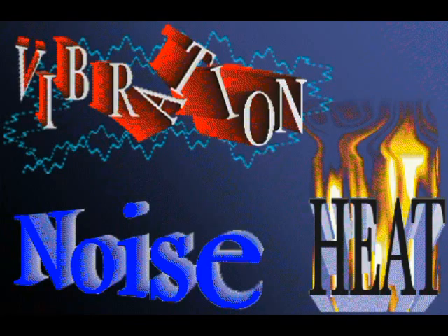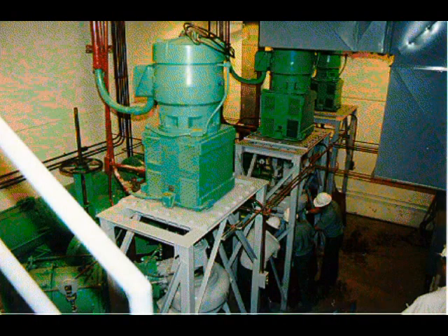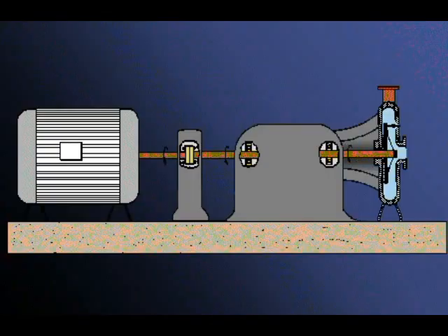Generally, noise, vibration, and heating are all indications of a problem and should be investigated immediately. If pump performance is not satisfactory, it may be necessary to run a pump performance test, possibly with the aid of the manufacturer's representative. Before this course discusses different kinds of pumps in detail, it will examine some components which are common to all pumps.